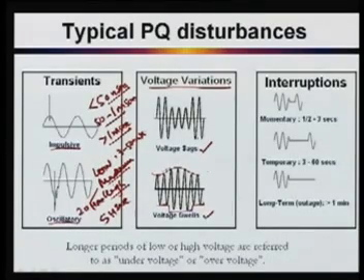Let us come to the first voltage sag. Similarly, here the voltage was this magnitude in the steady state, and suddenly the voltage is reduced and then it is again following its normal voltage. So this is known as the voltage dip. Again, this voltage dip is categorized in three categories. One is instantaneous, another is momentary, and the third one is temporary voltage dip.